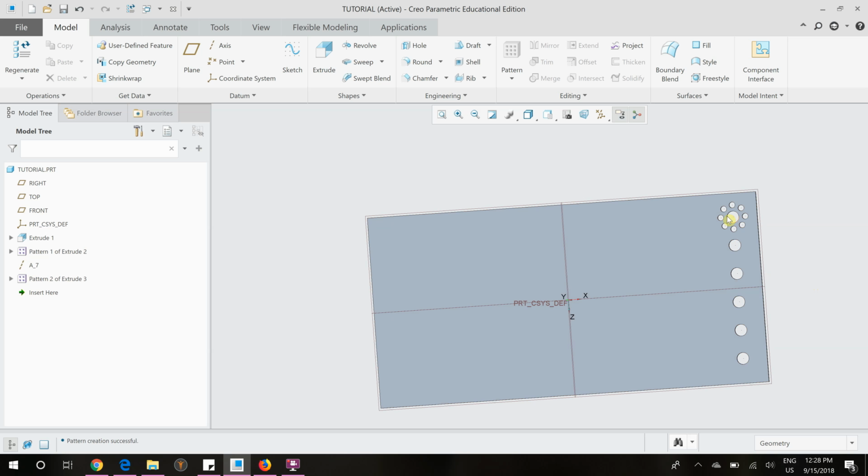So those are the basic pattern functions that you'll probably need to be using this year. You can play around with them. There are many different things you can do with patterns. For example, you could make this group of holes, and then you could have made a pattern of all 9 of these holes all the way down here. However will make it easiest for what you want. So that is patterns in an axis direction and in a straight line direction.